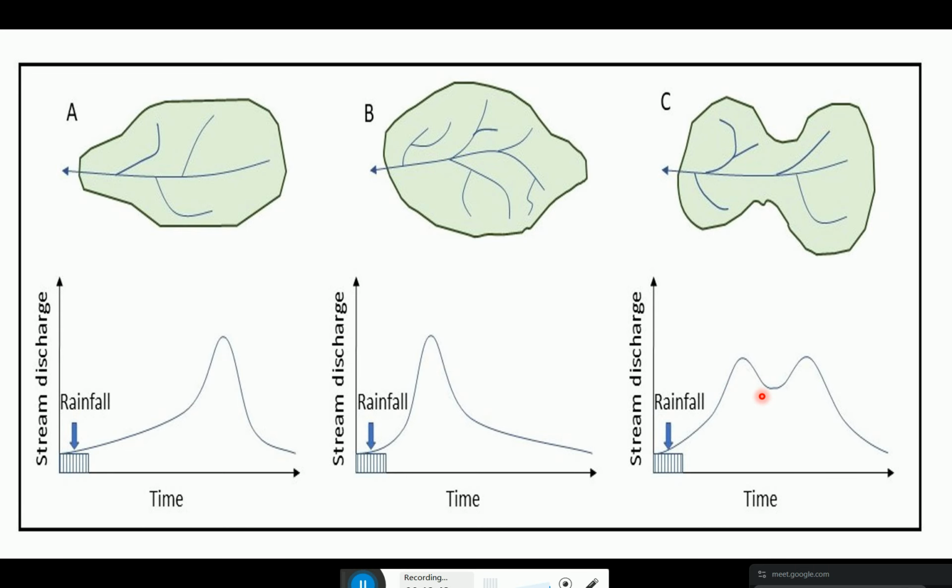Whenever you find in a statistical analysis, in a graphical representation, this type of graph, it is skewed, unlike a normal distribution. It is basically skewed, and the two domains represent that the data nature has changed from here to here. This is for a very large catchment area, where the rainfall intensity is different, so two types of peaks occur. Geographically and geologically the area is changed. That's why this hydrograph is basically called the heartbeat of your catchment area.